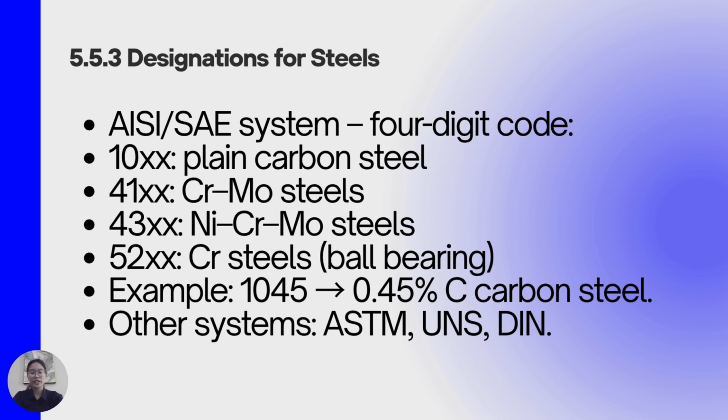Alloy steels such as 4140 or 4340 represent chromium-molybdenum and nickel-chromium-molybdenum steel respectively. These systems simplify communication between engineers, manufacturers, and suppliers globally.